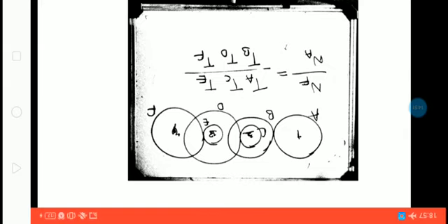Now you see, what is TA? TA is the number of teeth on gear A, and gear A is a driver. And TC, what is TC? TC is the number of teeth on gear C, but you see gear C is also a driver, an intermediate driver, such that C rotates D. Similarly, E is another intermediate driving gear such that E rotates F. So TA, TC and TE are teeth of driving gears. Similarly, B, D and F are driven gears.